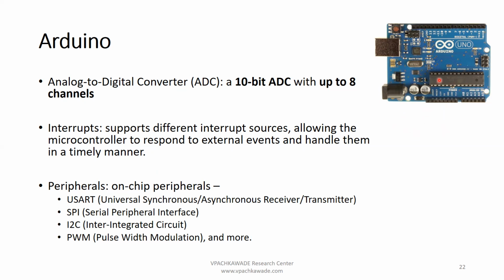So it goes to the interrupt section, and the microcontroller understands that it has received a request from the external world. According to the program, the microcontroller continues its current operation and at the same time allocates its resources to attend to that interrupt request, or it can stop the current operation and go perform the request received through the interrupt from the external world. That's the whole purpose of the interrupt section.